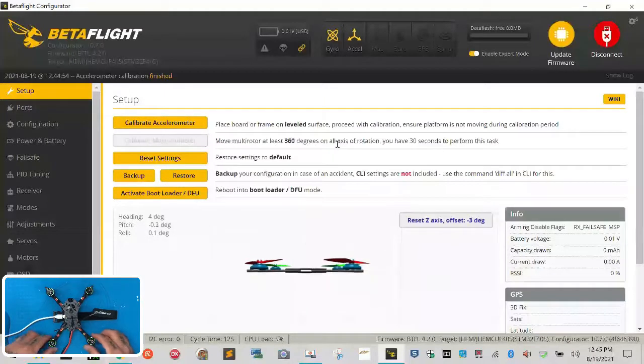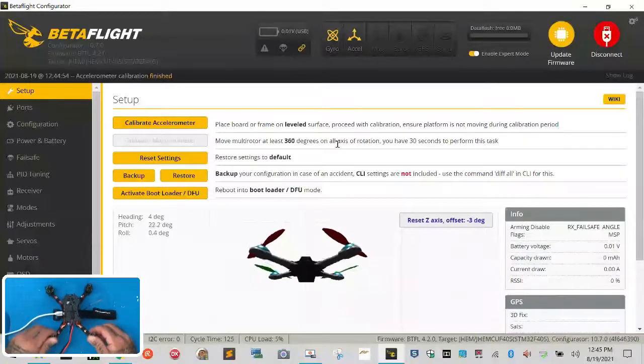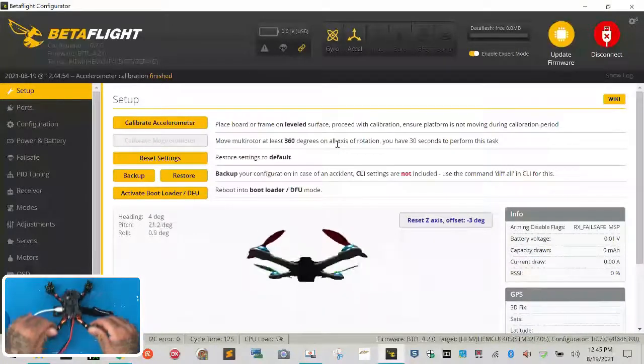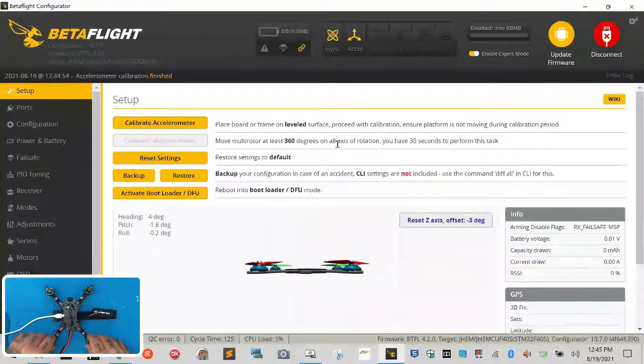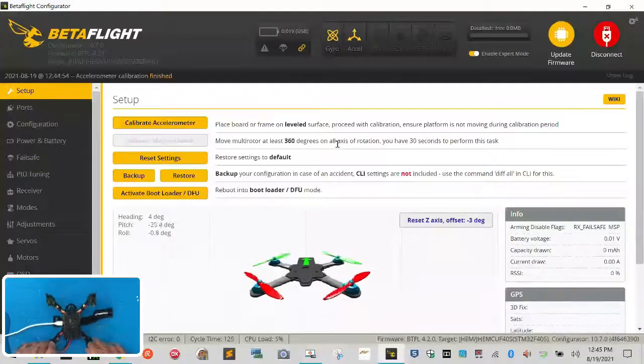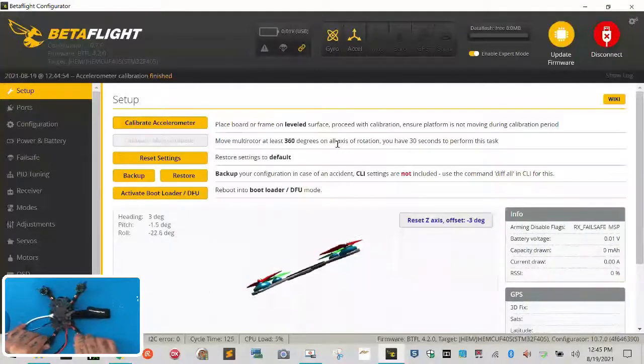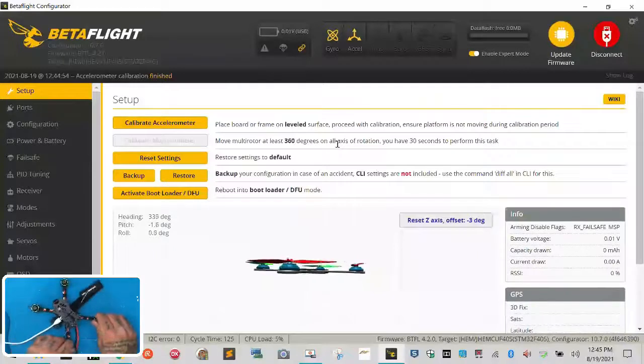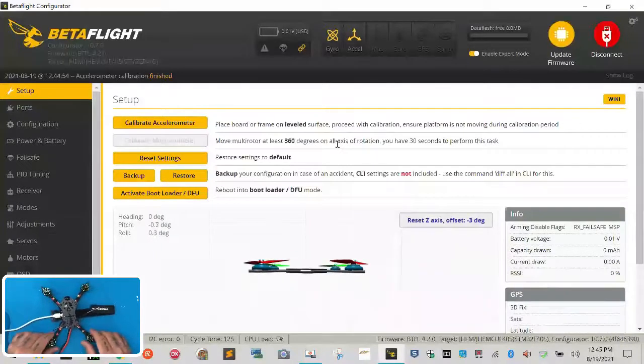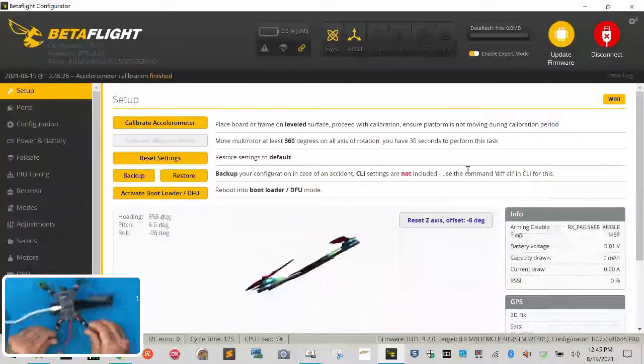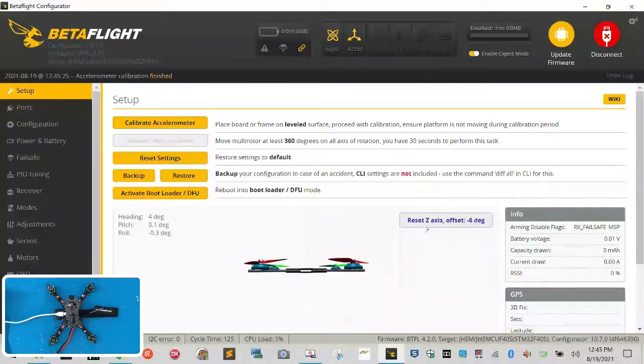Now, from your back motors, just grab the back motors and pitch the drone up, and you should see the drone on the screen mimic your drone. Okay, that's how you know it's configured properly and orientation is properly done. So then you can pitch it back, you can roll left, you can roll right, and then you can yaw these directions just to make sure. Once you're set, if everything looks good and it mirrors what you're doing perfectly, go ahead and recalibrate again just to tell it it's flat. All right, that's how you know you're set up. Okay, you go crazy, it goes crazy, you know it's wired properly.